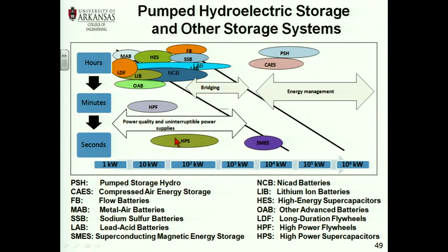High-power supercapacitors. This is something that, once again, we hear about using energy storage and supercapacitors. Once again, the supercapacitors are for a very short period of time. Honda had an electric vehicle with a fuel cell, and it has supercapacitors. Why were they there? Because the fuel cell cannot provide power changes instantaneously. It takes a while, because of the way that the fuel cell works, to go from 10 kilowatts to 15 kilowatts.